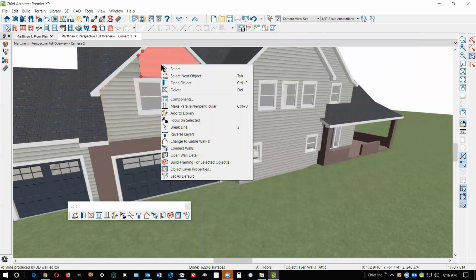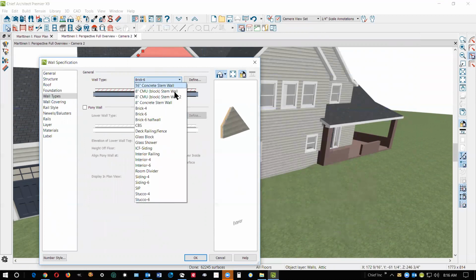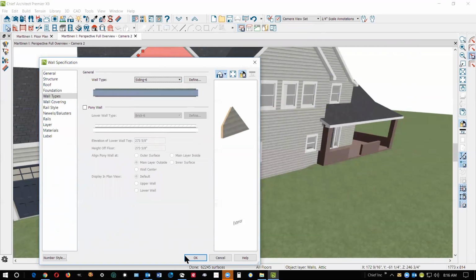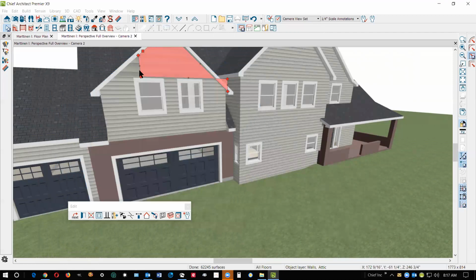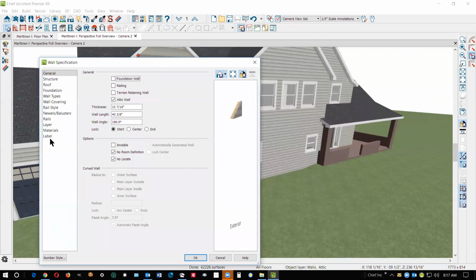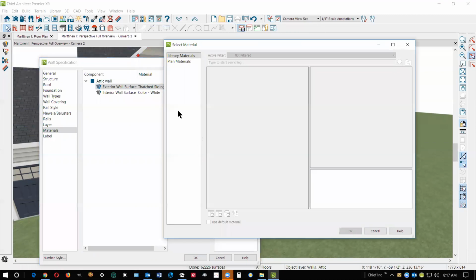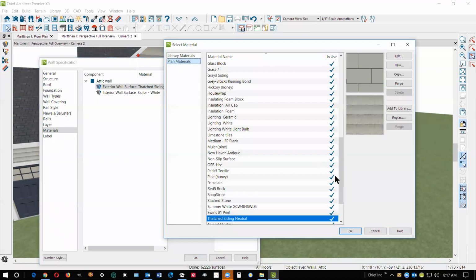Okay, and these attic walls just kind of follow lockstep with whatever you do on the floor below. So we'll just straighten those out. I see brick 6. It doesn't make any sense. So siding, whoops, not interior 6, siding 6. There it is. So you had some out of agreement settings, and I think you tried to fix it after the fact without changing defaults, and that's what got you into trouble.